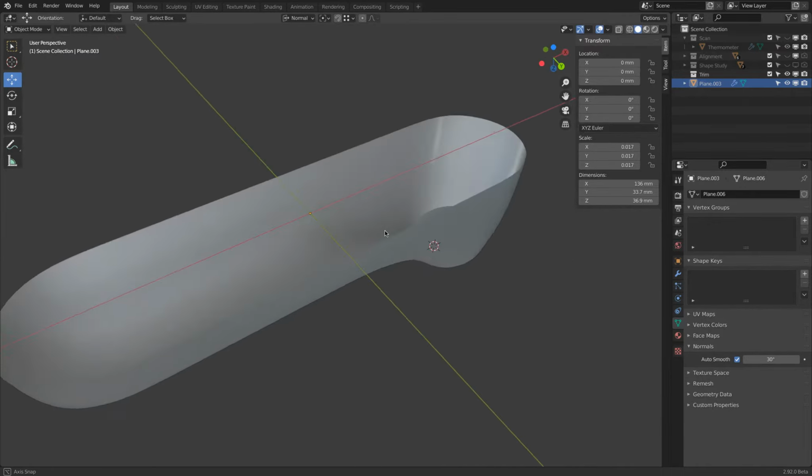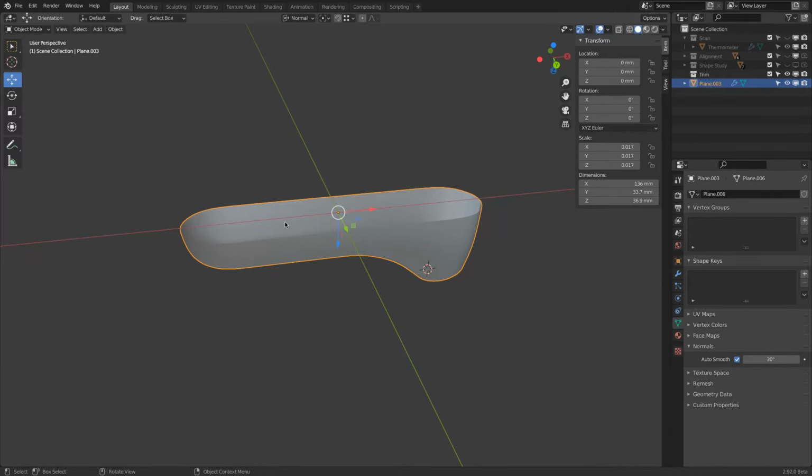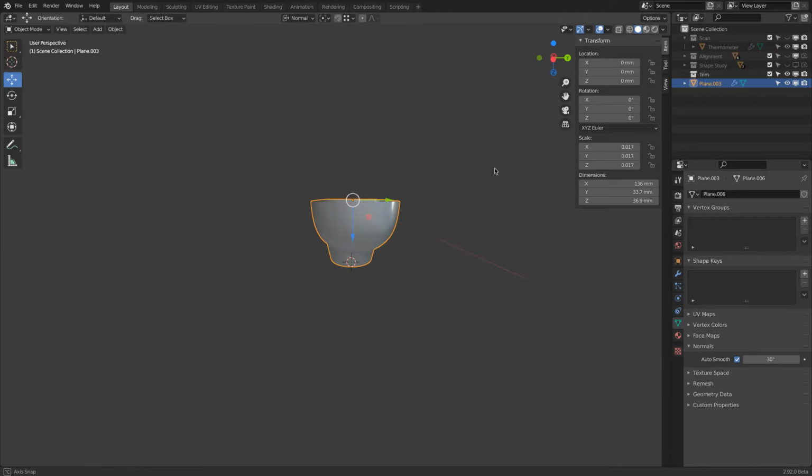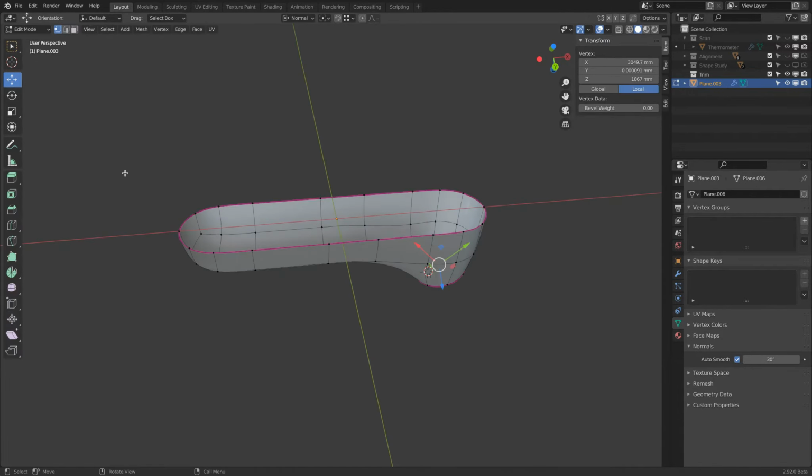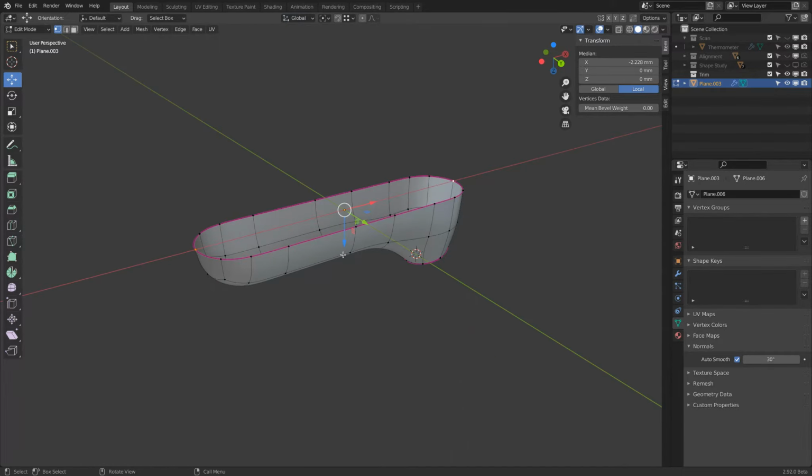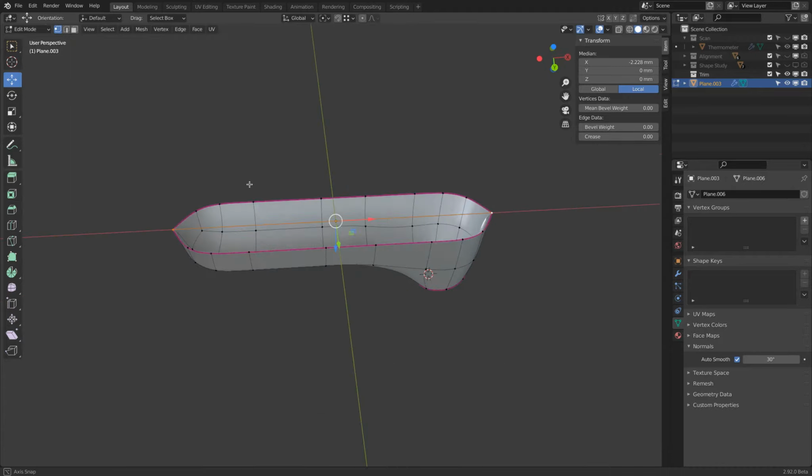Okay, now let's take a look at the bottom. How can we cap this? We want to cap this and maybe add a very gently domed surface. So we go to edit mode, and then we can select these 2 points. We want to go to transform orientation to global now, because all we want is just move points straight up and down, and press F.